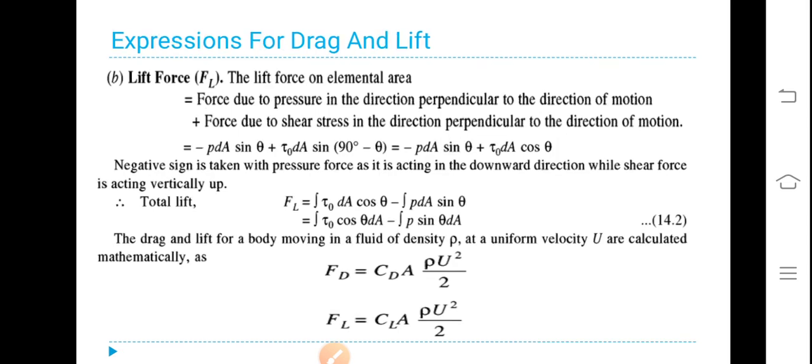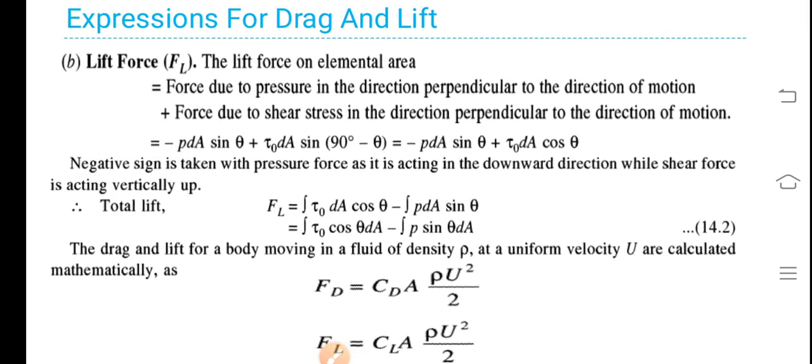Lift force FL on an elementary area is equal to force due to pressure in the direction perpendicular to the direction of motion plus force due to shear stress in the direction perpendicular to the direction of motion. That is equal to minus P dA sin theta.